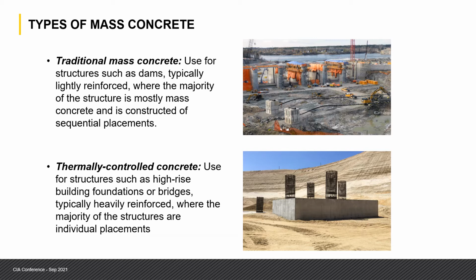And not only is it going to be heavily reinforced, it's going to be typically isolated structures, not going to be like a dam. It's going to be isolated, but also you're going to have much higher strengths. The strengths are likely going to be, at early age, much higher than what you expect in traditional mass concrete.